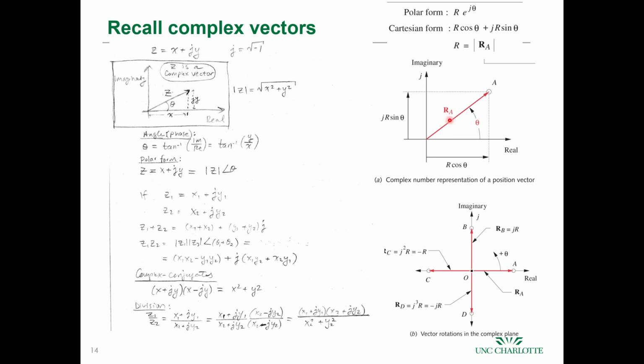And if you take these vectors, you can sum them through the linkages, and then you can take the derivatives and find the accelerations, velocities, angular velocities, and angular accelerations for these. And you can analyze them for your 4-bar mechanism, your crank and slider, or slider crank, and other mechanisms as well. What's interesting is if you use this approach, every time you multiply it by j, you're actually rotating